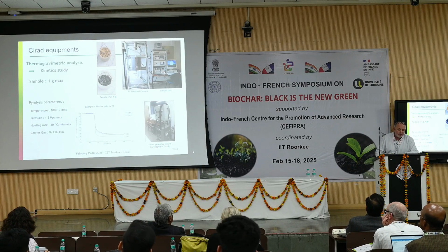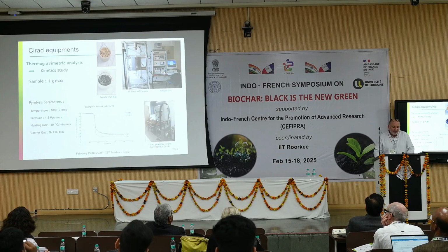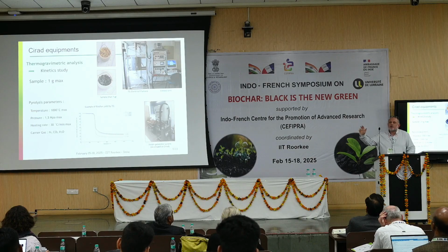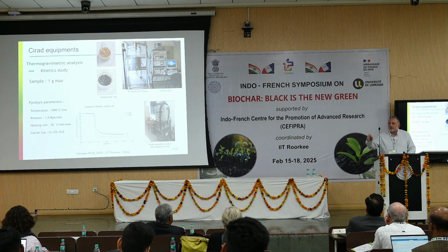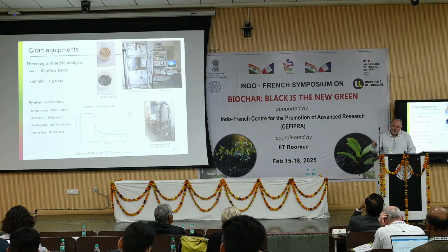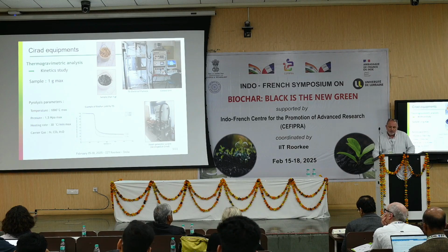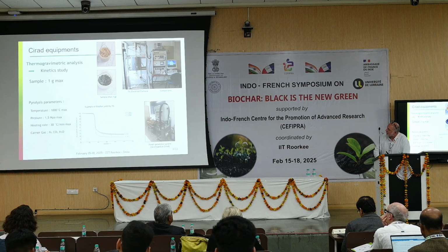So we have the thermogravimetric analysis with some samples. One interesting thing in this equipment is that we can work with different carrier gases, CO2 and steam. We constructed a specific steam generator in order to study the activation of biochar and similar things. And we can also work at elevated pressure. It's an older one we developed, and so we can work with different conditions.